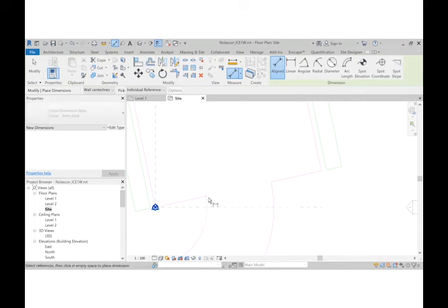DI is the shortcut key for checking distance. Perfect, 6,500, just as we had it checked in our CAD file. See, it's useless to keep going when you haven't checked and then find out later that you have incorrectly imported the file, right? So this step is very useful.